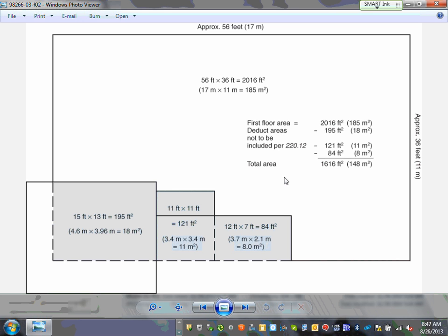So you deduct all these areas, porches if any, garages, all this stuff. And then the area that you're supposed to use right now is 1616 square feet. So what do you do, Derek? You take the 1616 and multiply by 3. That will be the allocated volt amps for lights for this house. Who cares? That's how you're going to size your panel.